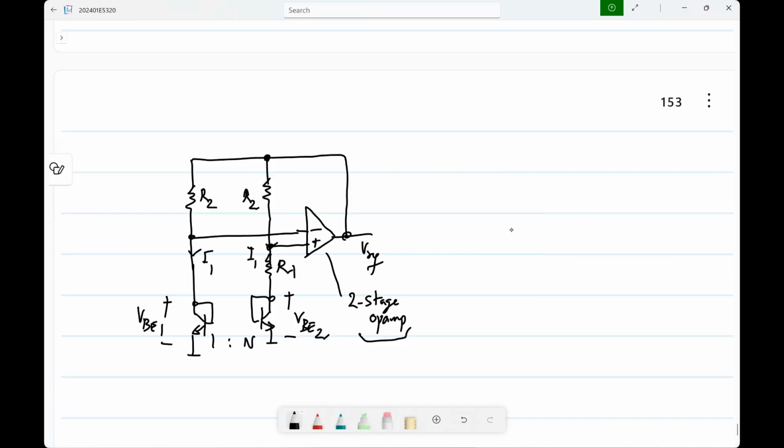Now, of course, if the op amp has an output stage that can deliver a large current, then you can connect your load directly here. That will be able to drive it. So that's also the reason to show this. Because negative feedback will make sure that this is VREF. But then if you try to, let's say, draw a lot of current and the op amp cuts off or goes into some undesirable region of operation, you will have a problem.